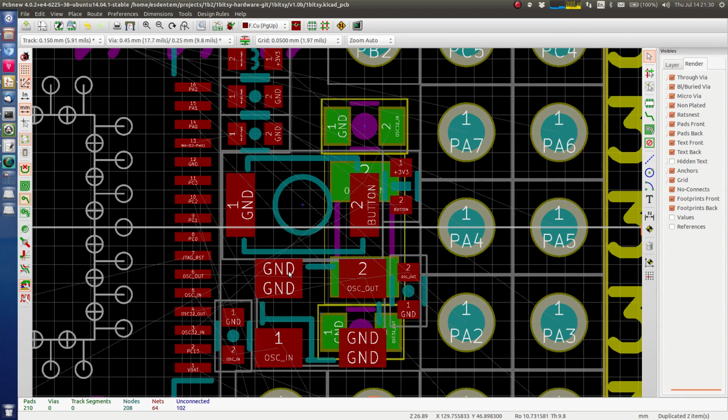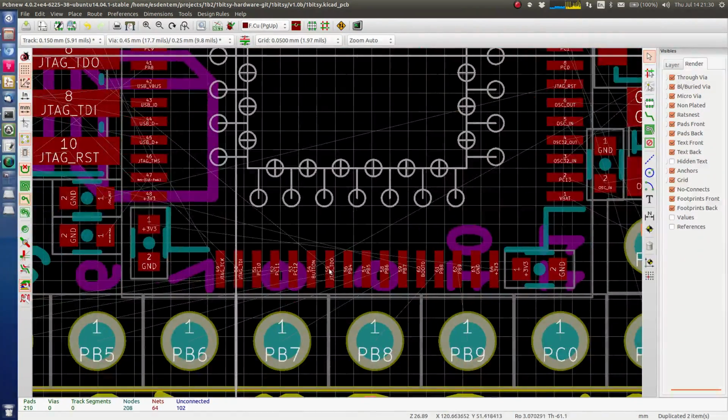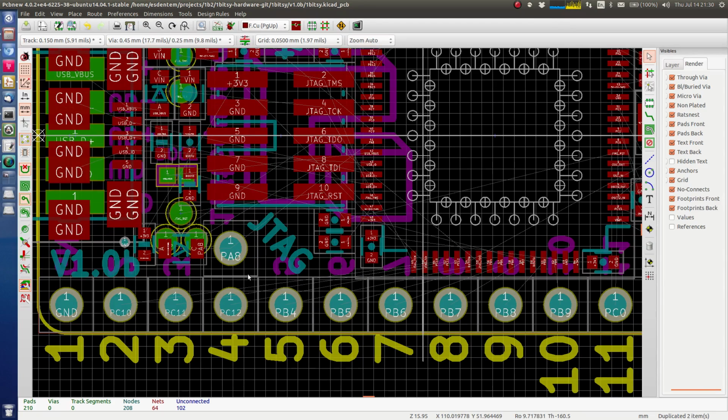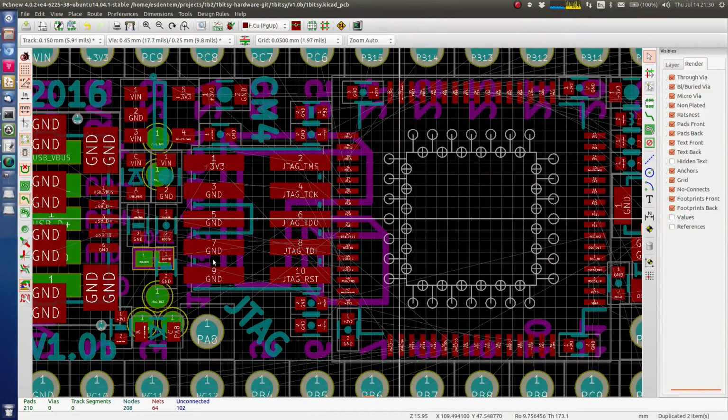Alrighty, so we have the button, and the button is actually connected to this pin down here. A nicer thing would be if the button would be here in this area. But the problem is that the LED would need that space. And I don't really want to move the LED up here, that might be closer, because then it is covered with the connector from JTAG that is in this whole area here. Problems. Yeah, I think I will just leave it as it is.